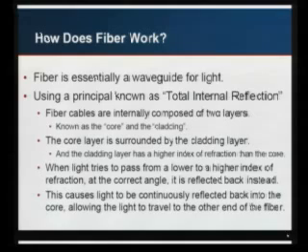And the way this works in physics is when light tries to go from one medium to another and it tries to go into a lower index of refraction, if it's below a certain angle, it gets reflected back in. And so having the core wrapped by the cladding keeps it from leaving the core. It keeps the light injected back into the core. And the only way it can propagate is through the fiber and out.